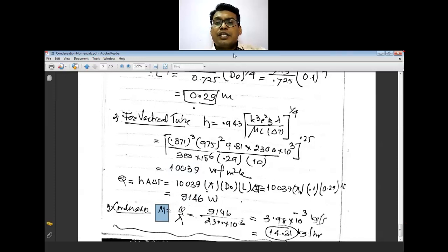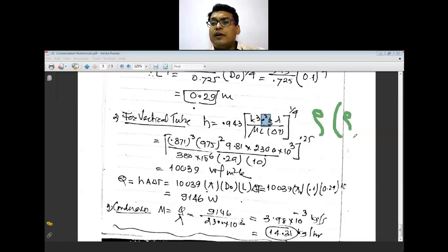Now, in addition to these formulas, we have also discussed some formulas. Then there is a density correction that is also added in some books. So this is getting modified as, instead of writing the rho square, it becomes rho into bracket rho of liquid minus rho of vapors.